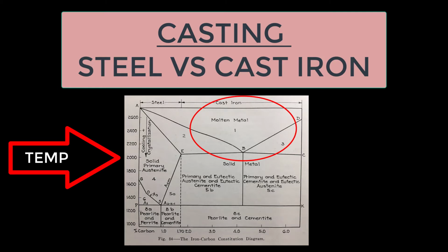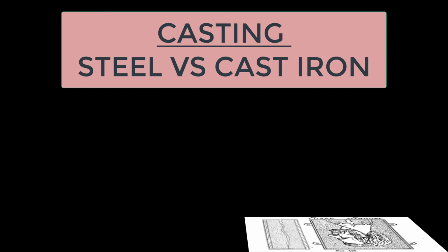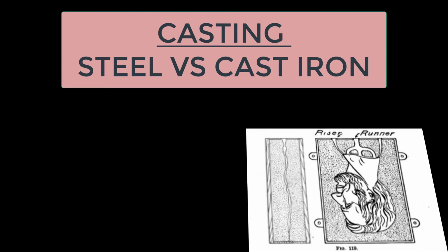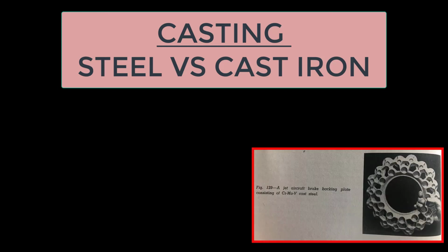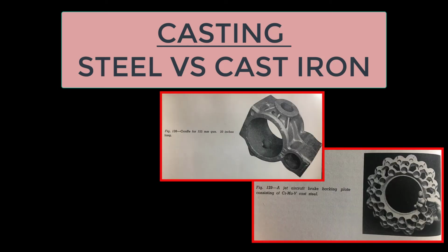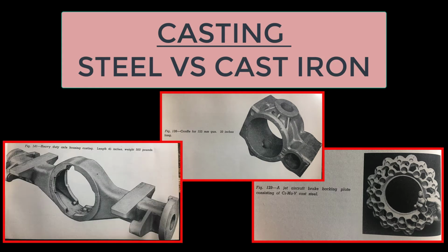If you have a complex mold shape, cast iron is more likely to fill it up and get in all the right nooks and crannies, right? If it's some goofy complex shape, then cast steel is. Cast steel can be designed to fill up a complex, funny shaped mold, but it just takes a lot more thought and planning and engineering time to really get it right.